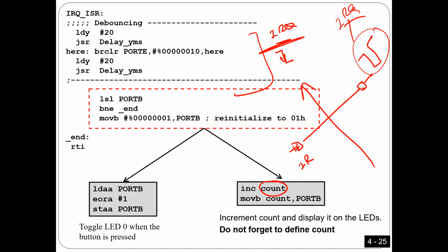So if you use register A or register B, and the initial value of A is 0, it's going to stay 0 forever, because once I leave the subroutine, I put the initial value back. You got what I'm saying? So if you want to recall how many interrupts, it has to be a memory location. Any questions?